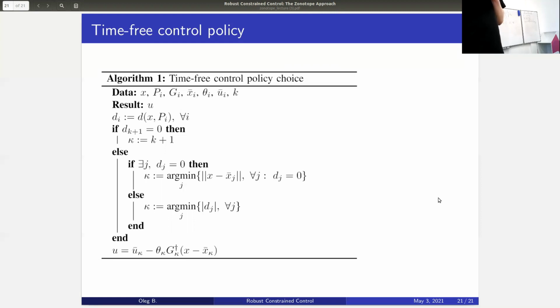Because if we know we're here, something can happen to us, and we'll be here, or nothing will happen to us, but also we will have some disturbances in our measurements. We want to have guarantees not just for this exact state, but for all of those states, and that desire guides us towards the set representation. That's actually what explicit MPC is all about, or finite time stability is all about. You want to have guarantees not for one state, but for a set of states.